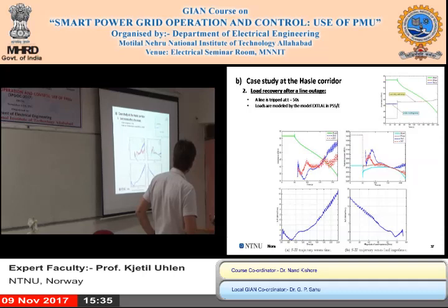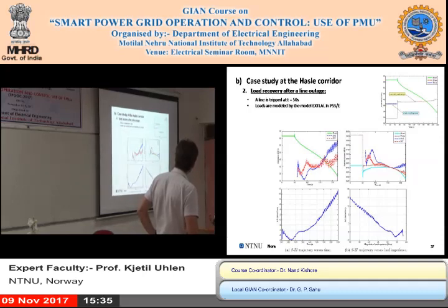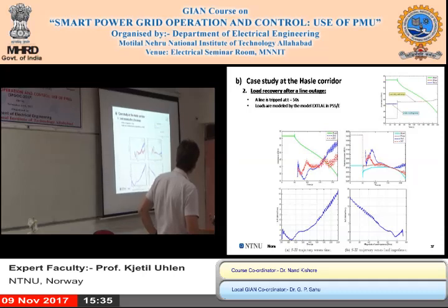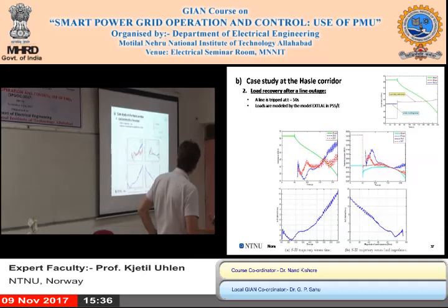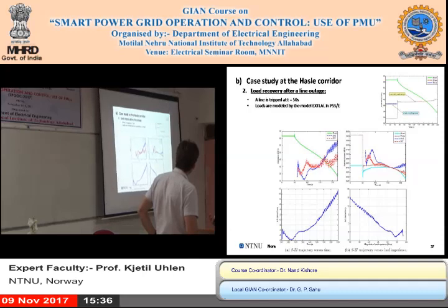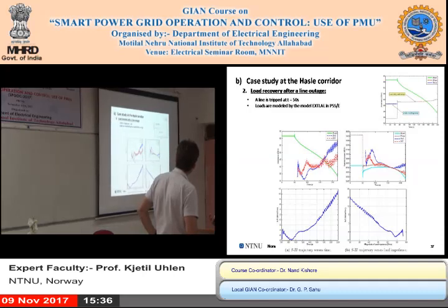So in this case, we are running steady, and then we have a line outage, so that the Thevenin impedance is much higher than before, and this is the estimate and the load and the maximum loadability here, and this is more detail on the various methods. Again, it looks like they do cross at the same time, but not always exactly at the maximum power transfer.